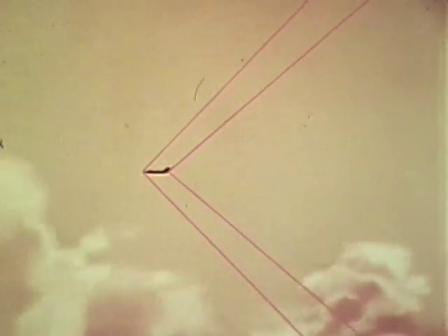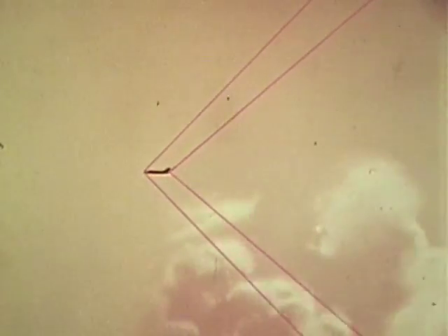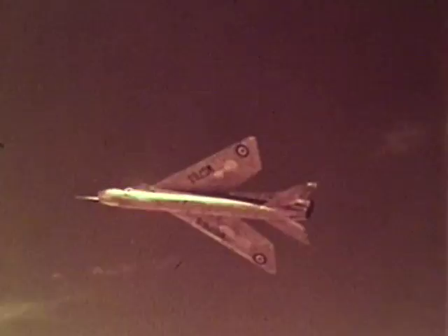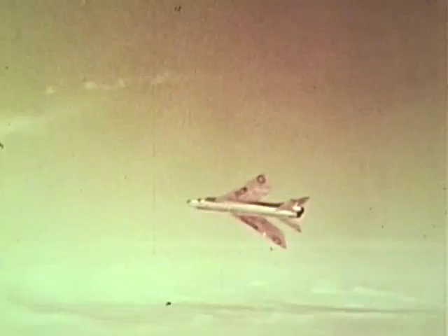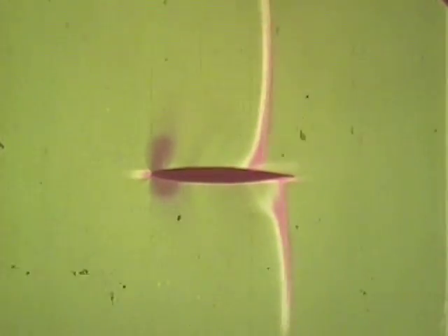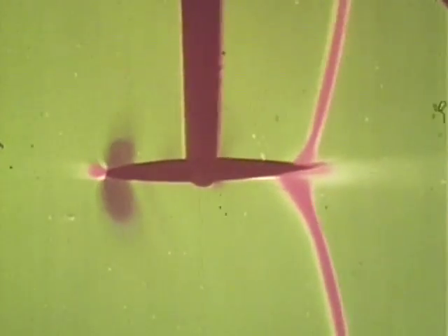The same sort of thing may happen with an aircraft flying at a steady speed above Mach 1, either transonic or, as here, supersonic. To reach the supersonic speed range, all aircraft must pass through the transonic range where shock wave troubles are at their worst. Slight changes in speed or in attitude make the shocks move violently.